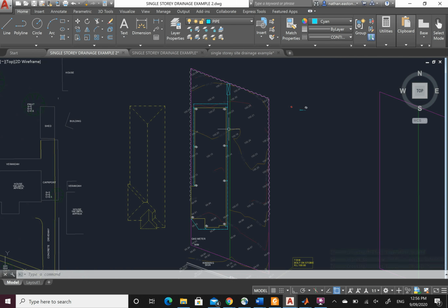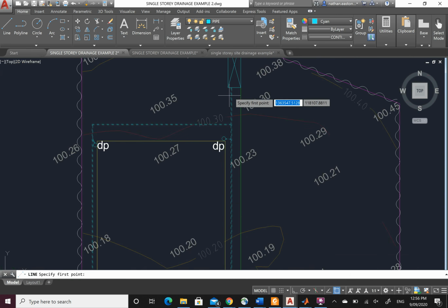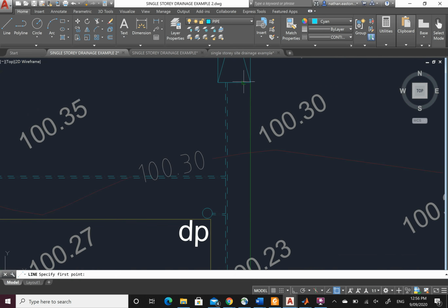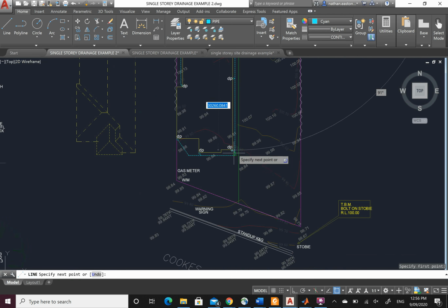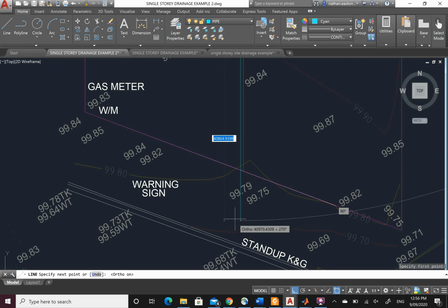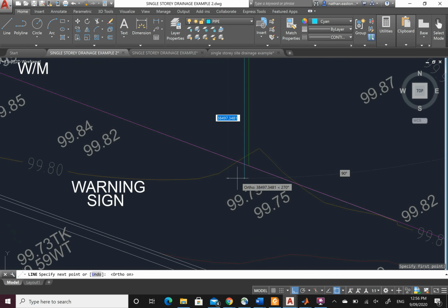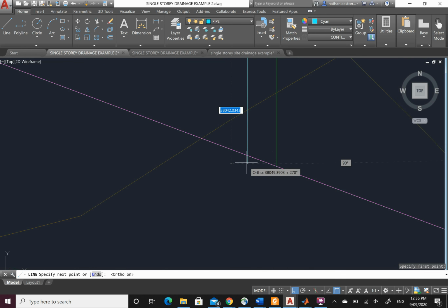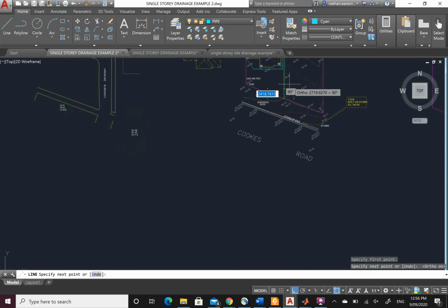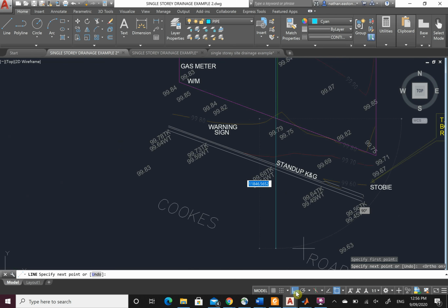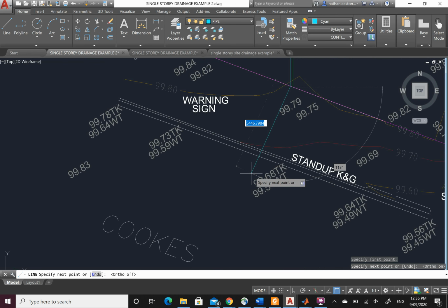So all the water collected from the roof comes to the tank. And then what happens? Well, like I said, from the tank, when the tank fills up, we discharge to the stormwater. Straight line, gets me to here. So to about there somewhere. And then I don't have information here about the stormwater outlet, but it's going to be somewhere about here.